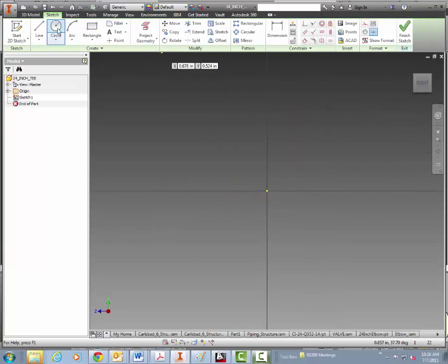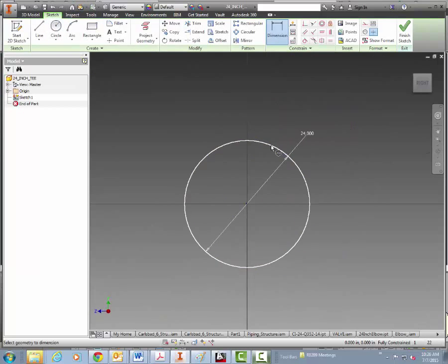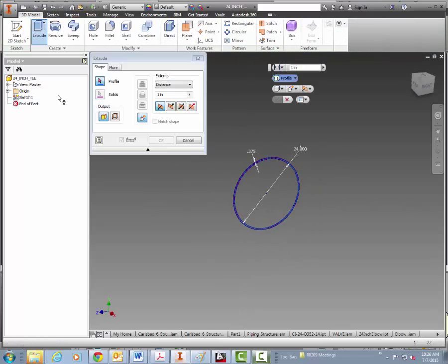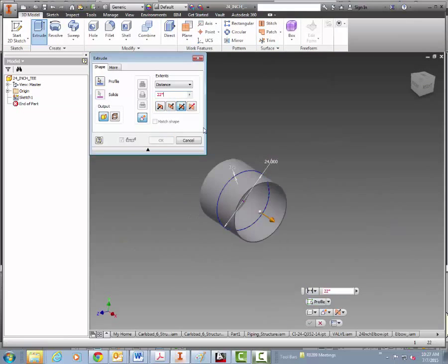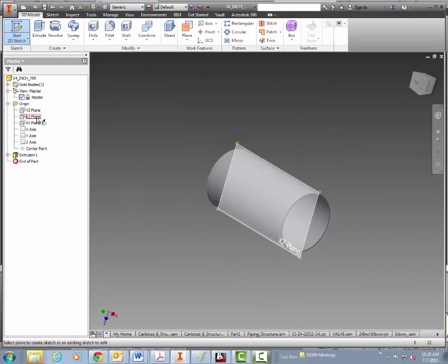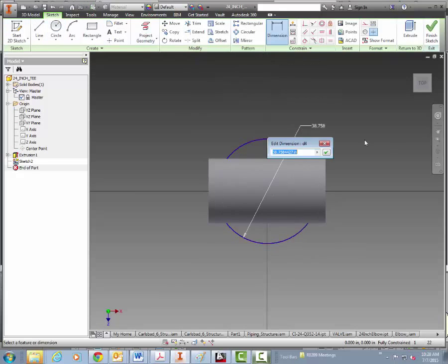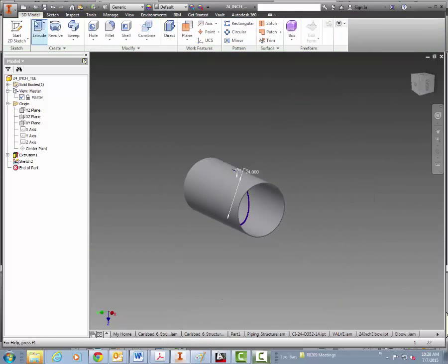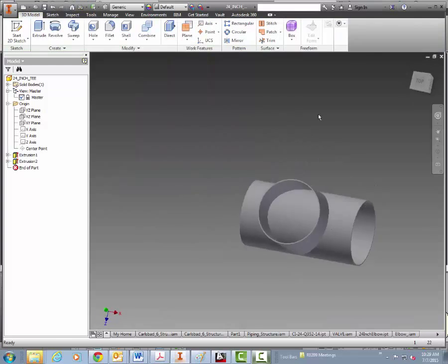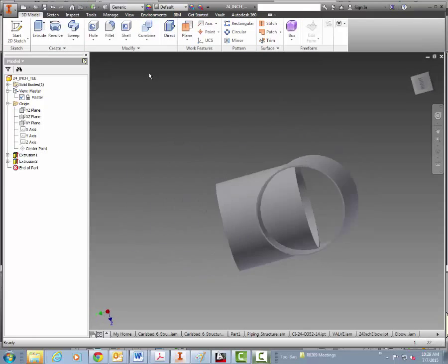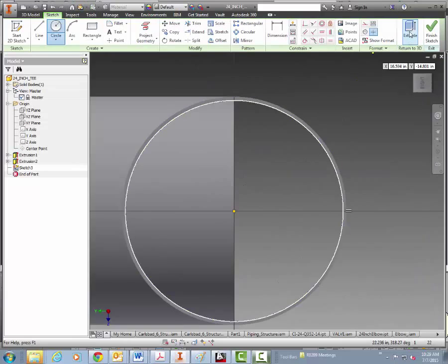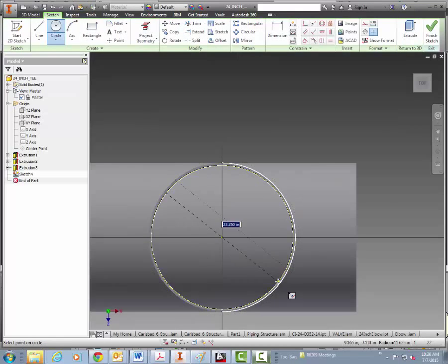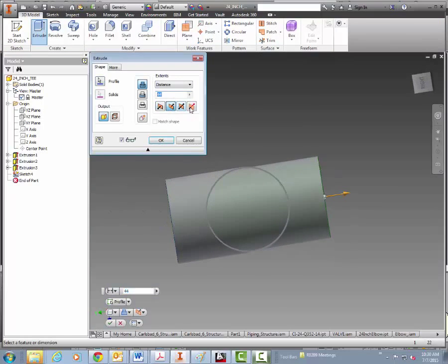Now we're going to go ahead and make a T. The T again is from AWWA standards. We create this by creating a sketch and then extruding that sketch across the required planes. Once the parts have been extruded, you'll notice that there's some conflicting parts in there, so we need to go in there and remove them. We'll do that by extruding and subtracting, or using what's called Boolean subtraction.